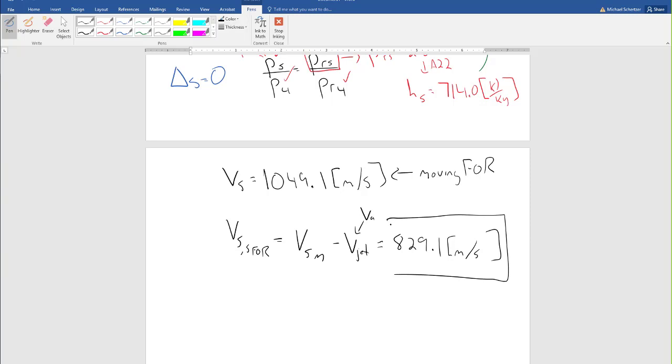Now, you could get different permutations of the known information that you have, but the key points about this turbojet problem to do it correctly are you have to get your units right with kinetic energy. If I ask you this problem and it's imperial units, it will be harder than if it's metric units, right? Because then you've got to divide by gc, then you've got to divide by 778 probably, right?